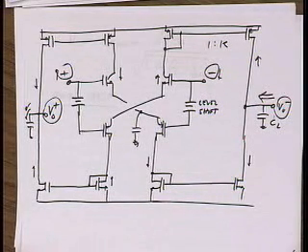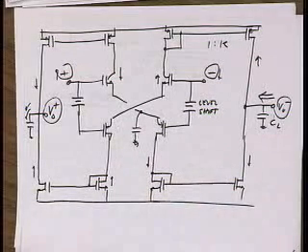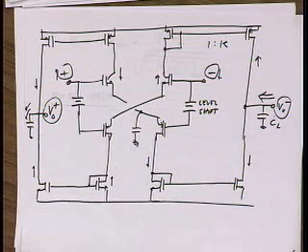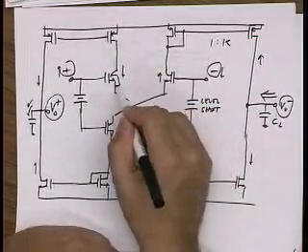And so you're laying it out. When you lay things out, you think about issues. What are you going to do to the body connection of these transistors? So you have the option of a triple well process, so you can choose whatever node you want for both the NMOS and PMOS. Where would you tie the body connections? Well, your first instinct is to get rid of the body effect, right? So you would just do this, right?